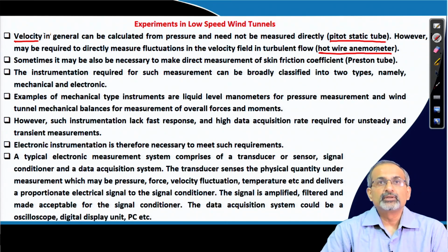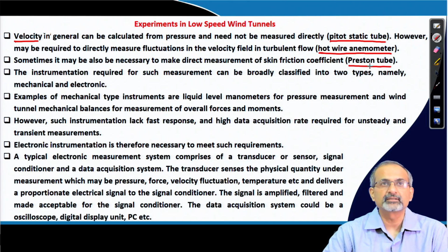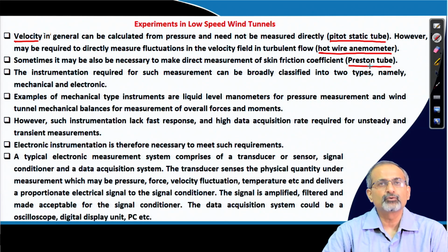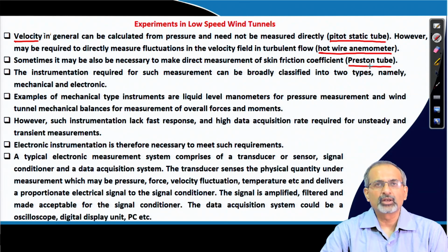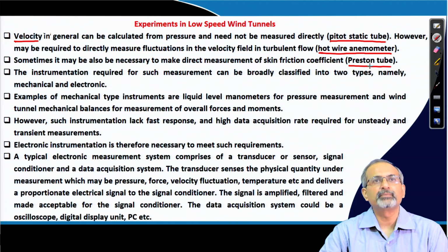Sometimes you may also be required to make measurements of skin friction coefficient, in which case we use a device which is called the Preston tube. Therefore, we need to have knowledge and availability of alternative instrumentation for the kind of experiment that we plan to do.